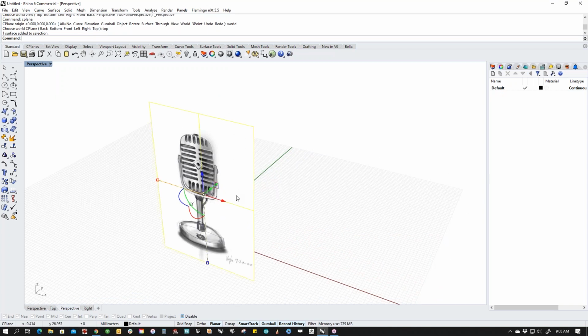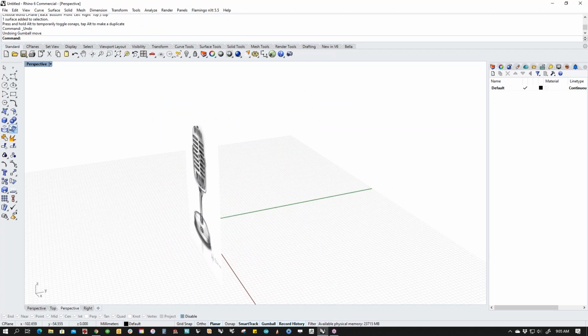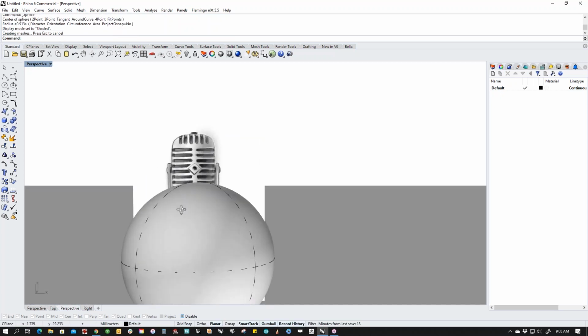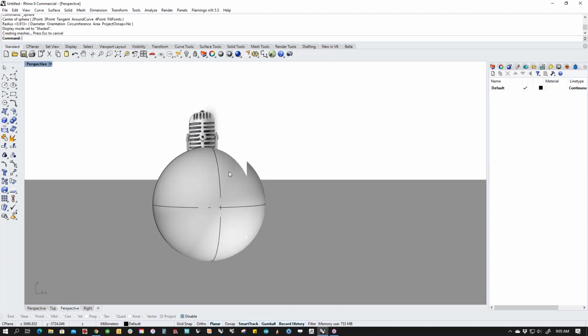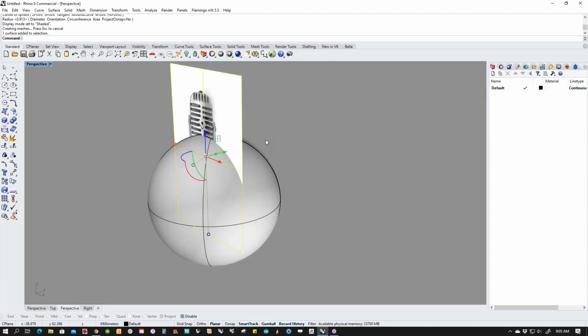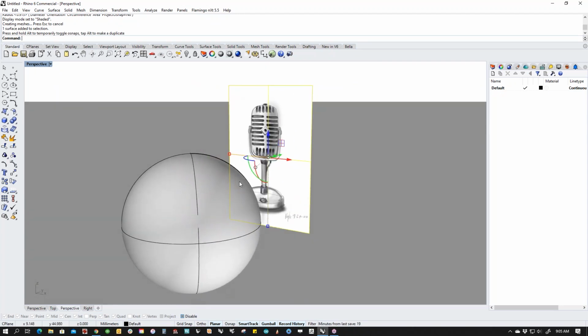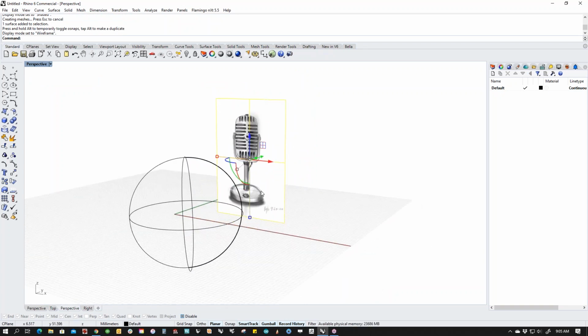So I'm going to just take this image, and I'm going to slide it back in space. And the reason that I'm going to do that is if I were to model, especially in a shaded view, and I were to leave the image at 0, it puts me in a position where the image goes right through the center of the scene, and I don't like that. So I'm going to take the image and slide it back out of the modeling envelope so that I can see the image as I'm working around it, and then stick it back there in space so I don't have to deal with it.